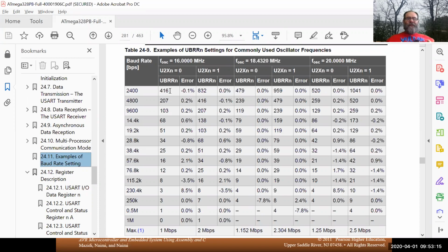So my gut feeling is if it was 0.1% at roughly 10,000 baud, you could probably do 1,000 characters before you had a problem. If it's 0.2%, you can probably do about 500 characters before there's an error. In order to avoid that, every 400 characters as you're transmitting, you would need to put a delay of a millisecond when you didn't transmit anything. The receiver would read that as an idle time. And then when you did the start bit again, it would be back in sync exactly.